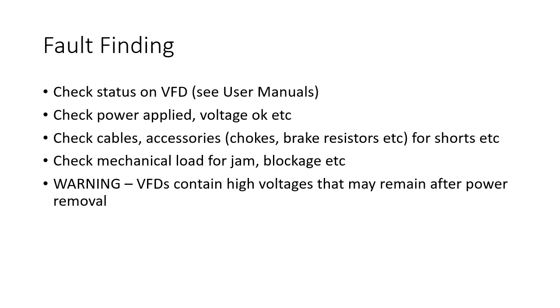You might also need to check the actual installation. Cables and accessories might need checking. For example, the chokes and the brake resistors in particular may have shorted or overloaded and burnt out. Of course, check the mechanical part as well. You're checking for jams, overloads or blockages.